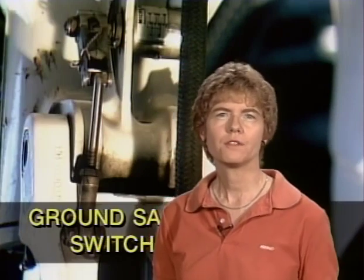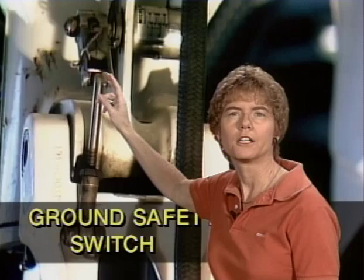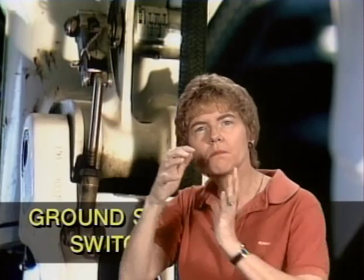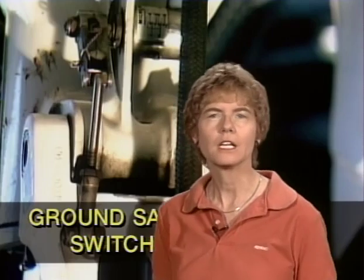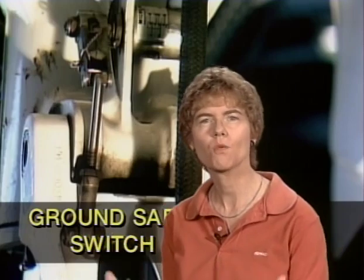Now, there's also going to be a ground safety switch. The ground safety switch is located on the main gear shock strut, and it's actuated by when that strut compresses and extends. It extends fully, of course, once the aircraft has taken off and it's in the air. This ground safety switch is very often called the squat switch.